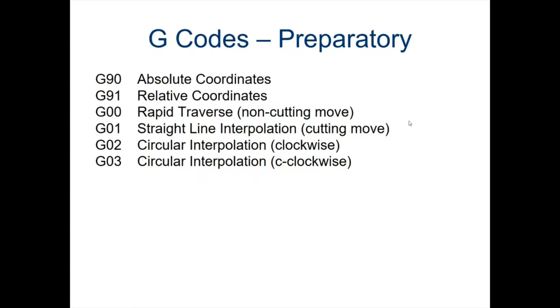So if we want to cut an arc, these are the ones we have. If you look, it says circular interpolation, and that is important because when we use this, it has to be a circle. That causes some problems in some cases. At the very least, it may cause some of your code to be really long, because if I want to do any sort of an arc, I'm going to have to put it together either as a bunch of little pieces of a circle to approximate some arc that is not circular, or I have to make sure that my cuts are circular. And you'll see that in a lot of parts. A lot of parts will have circles as opposed to other shapes that they could have. Not necessarily for this reason, but it definitely makes your G code easier if you use circles.